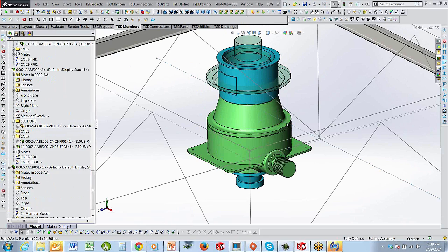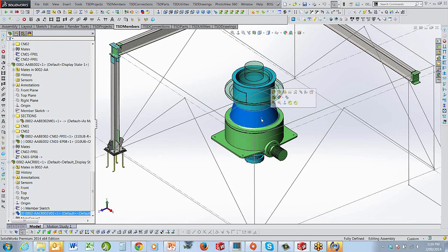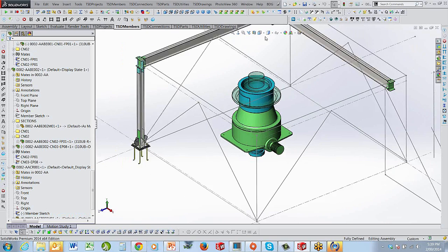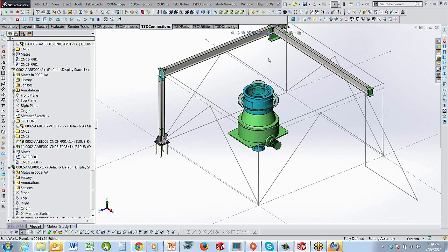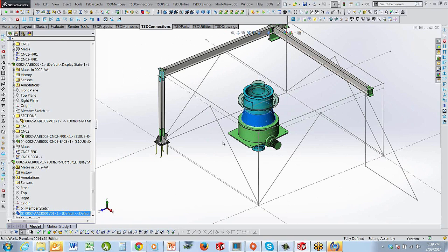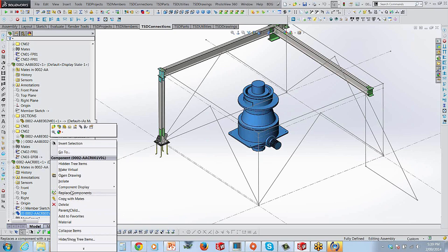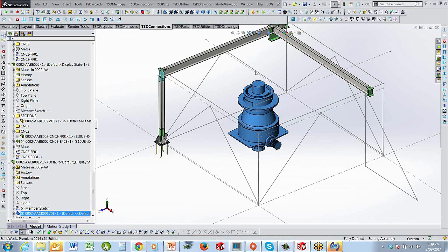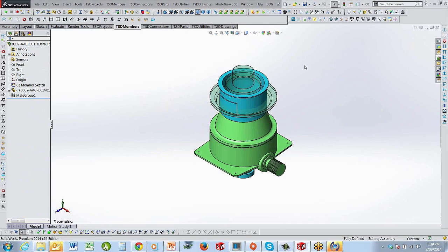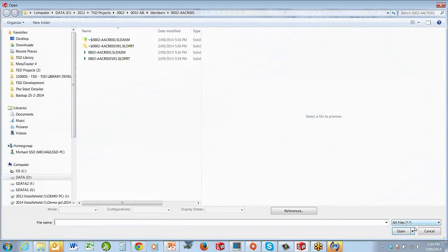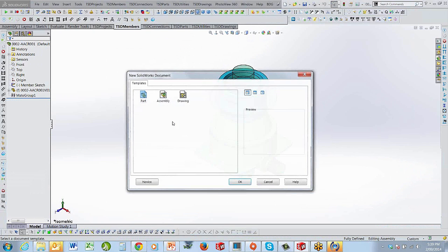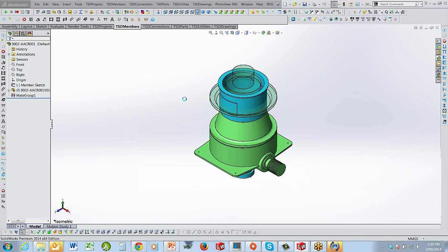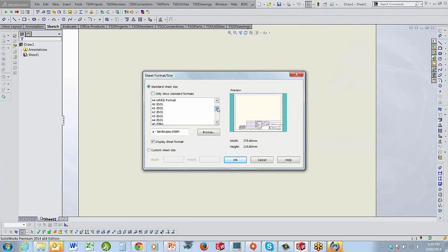So now I've filled in the custom properties for that vendor item. Okay. Now the vendor item will be picked up in the bill of materials when we go to do a lock on certain members. In this case, that doesn't have a drawing associated to it, I don't think. So we can just right mouse click and just check. No, no drawing. Okay. My vendor items, I like to put a drawing in there because with the drawings, maybe at this level it might have a drawing. You'll get a BOM. No, there's no drawing. So I'm just going to make something here for a drawing. So we've got something. How bad am I? I haven't even got my drawing templates hooked up here.